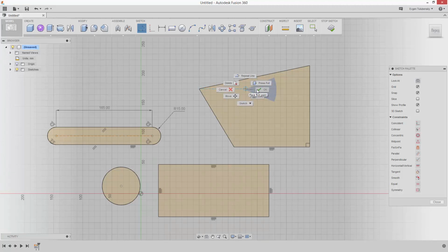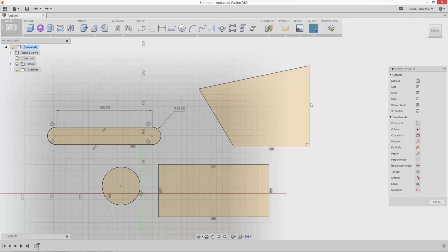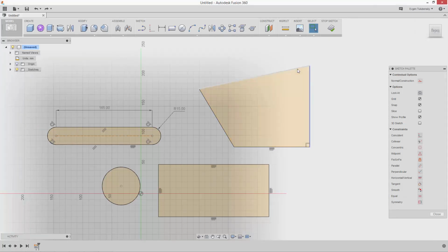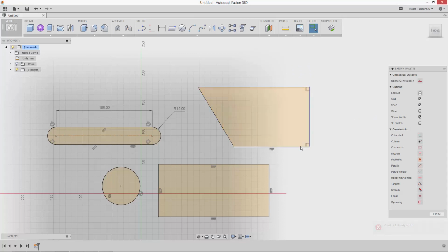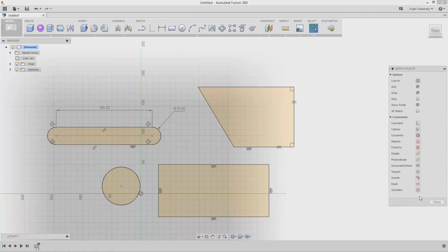Look at the Constraints panel. Select these two lines, as shown. Select Perpendicular. Feel free to experiment with other constraints between the lines. Select the next two lines as shown. Select Equal. You see how you could create more intelligence in the models with relationships.